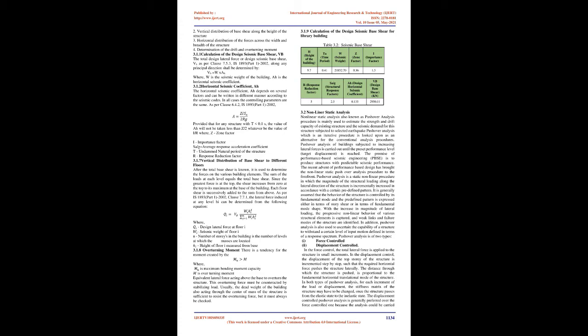Pushover analysis is a series of incremental static analyses carried out to develop a capacity curve for the building. This procedure needs the execution of a nonlinear static analysis of the structure that allows the monitoring of the progressive yielding of the structural components. The building is subjected to a lateral load. The load magnitude increases until the building reaches the target displacement. This target displacement is determined to represent the top displacement when the building is subjected to design-level ground excitation. Reza Ainul Hakim, Mohammed Sahib Alama and Samir Ashour, 2014.